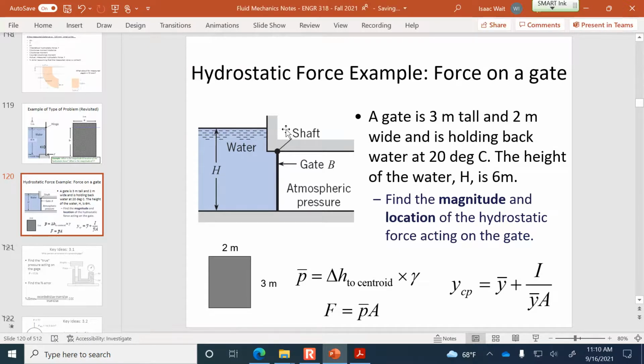What it's really all about is what's the pressure at the centroid. And the pressure at the centroid is going to be the same if there is water straight above it or if you have to go sideways and then up. Because remember, when you go sideways, the pressure isn't changing. So it's okay that we have to go a little bit sideways and then go up to the water surface. Because that horizontal movement from one location to the other doesn't affect the pressure at the centroid.